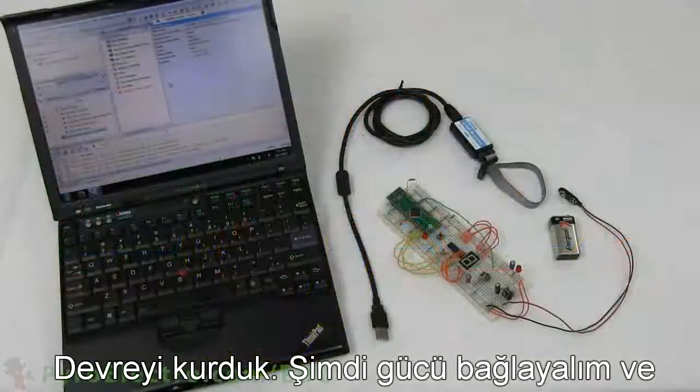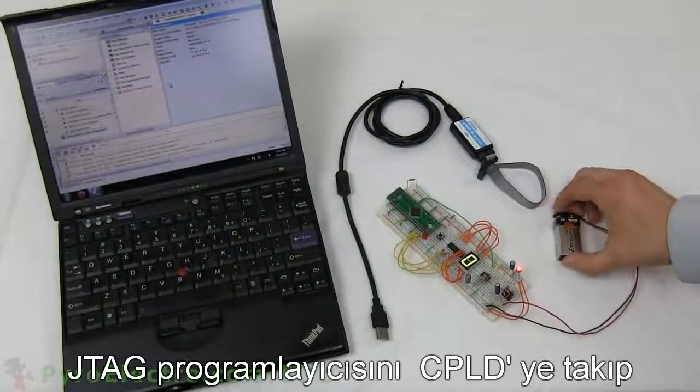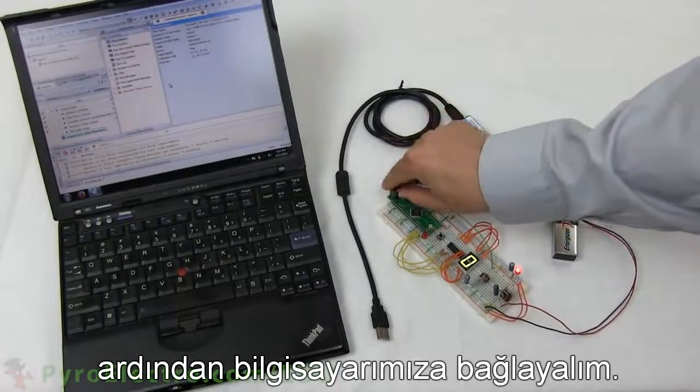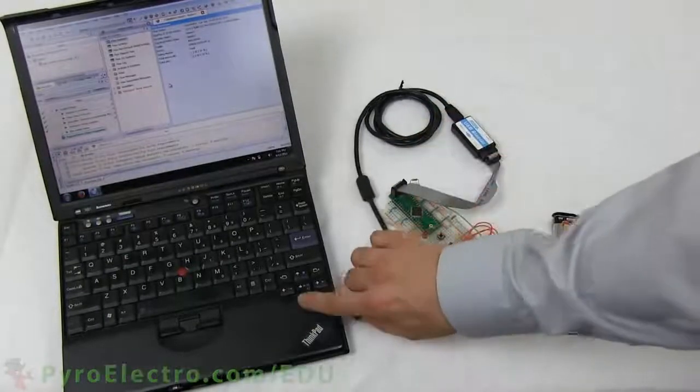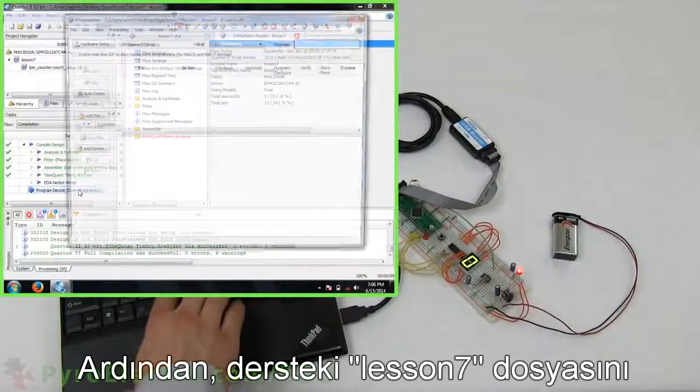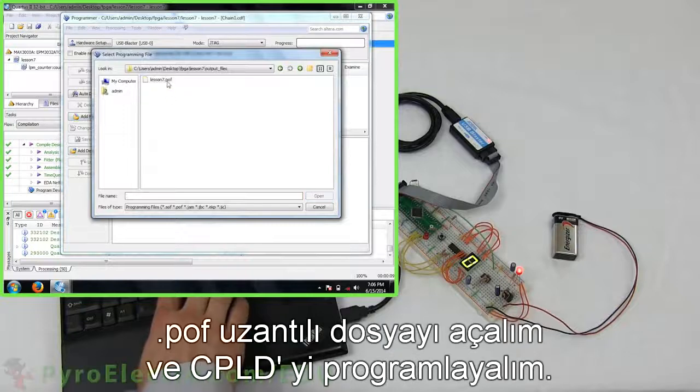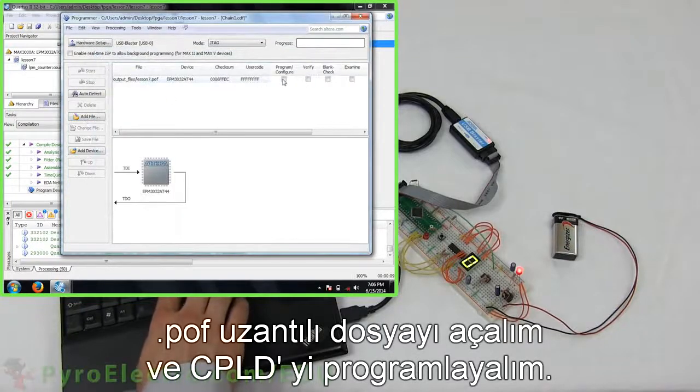Now with the circuit built, let's power it up and connect the JTAG programmer to the CPLD board as well as to our laptop computer. Then open up Lesson 7 in Quartus and using the programmer tool, find the .pof programming file and program the CPLD.